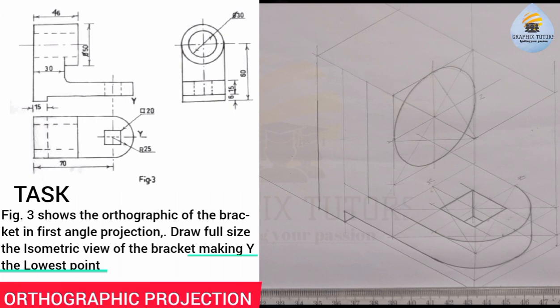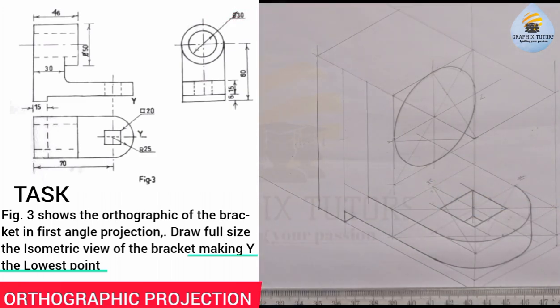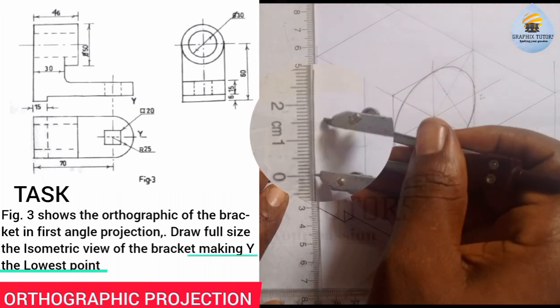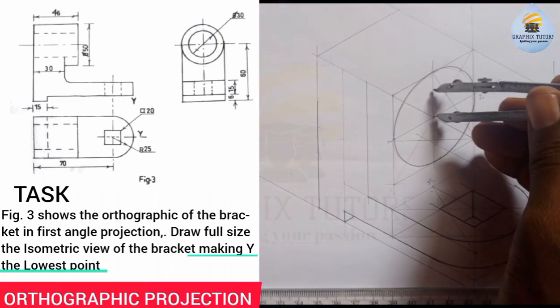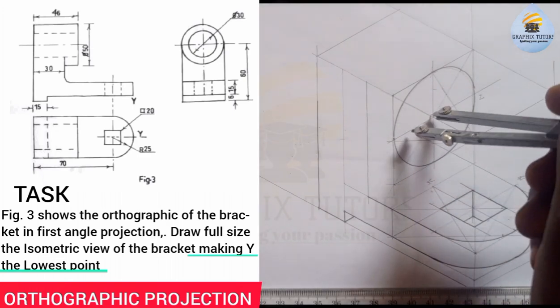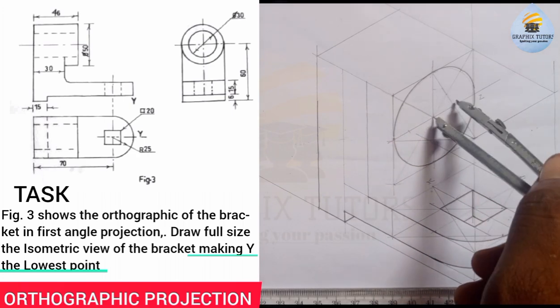There's still another internal circle that has a diameter of 30. So I'll just take half of 30, which is 15, right? I'll take half of 30 from here. You can see that. Half of 30, which is 15. So from 0 to 15 is from this point. You can see that. And I'll place it at the center point. I'll mark 15 up, 15 down, 15 to the left, and 15 to the right.